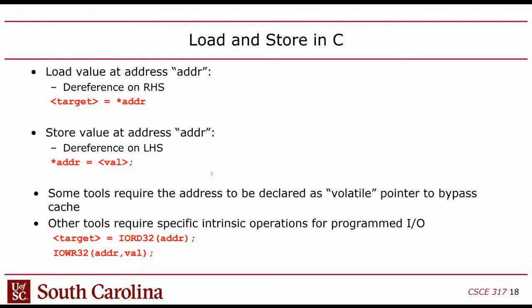How do you load and store in C or C++? You use the dereference star operator. If you do it on the right-hand side, it's a load. On the left-hand side, it's a store. And I mentioned that you have to be careful here because you can get burned. I've also been burned by this. I did this once on a MicroBlaze processor, and I didn't realize that you can't access I/O registers this way even on a bare metal system, because if you do, the cache will catch it, and there's no warning. You'll just get stale data. Boy, was that a hard bug to track down.